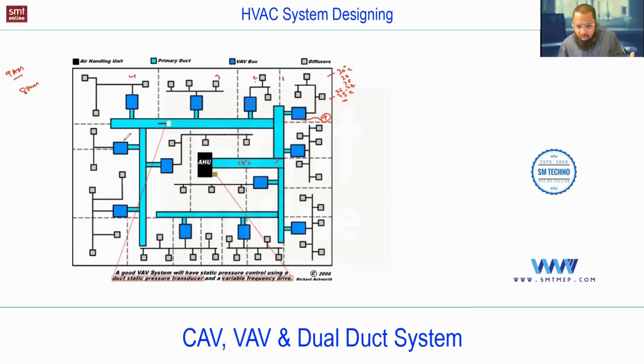Okay, now assume that all the VAVs are working. Suppose at 9:30 all the cabins are on, so all VAVs are working. So the AHU runs at full load, for example, and as the temperature is maintained, it will set to minimum. Or suppose one cabin switches off, so it will close, or be set to minimum.